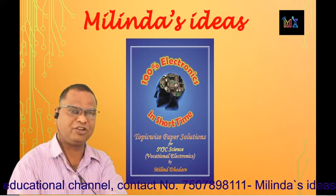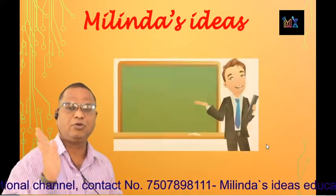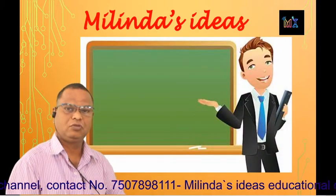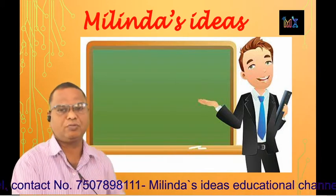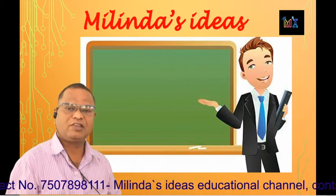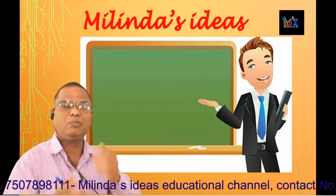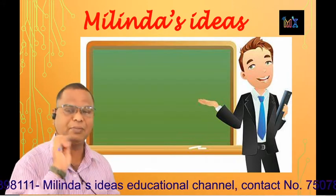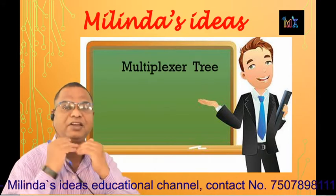Friends, in the previous lecture we studied multiplexer ICs, and we studied the IC 74153 because it is a part of our syllabus. That IC 74153 is a dual 4:1 mux. In that IC, there are 4 inputs, so 2 control lines are required. There is one output terminal, and to make the particular mux enable, there are 2 strobe inputs or 2 enable inputs. In this lecture, we are going to study the multiplexing tree.